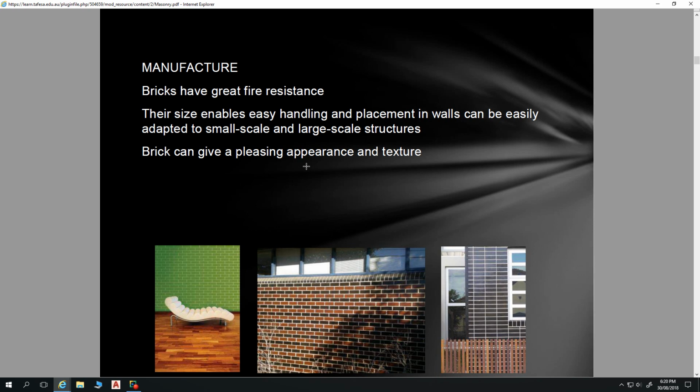But with cement bricks, if they haven't cured properly, they continue to shrink a little bit over time until they're fully cured. I was doing a final inspection before sign off for a place in Murray Bridge, and when I got there, the brick control joints, which are joints in your brickwork to allow movement and also allow some shrinkage, are meant to be 10 millimeters.